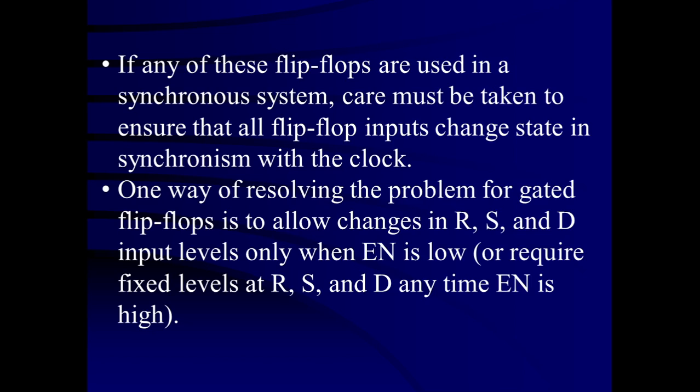You know the clock waveforms, right? We have studied the clock waveforms. That means for a certain period of time t1, it remains high. For a certain period of time t2, it remains low. So t1 plus t2 is the periodic time of this clock waveform. And as long as the flip-flop clock waveform is high, it remains enabled